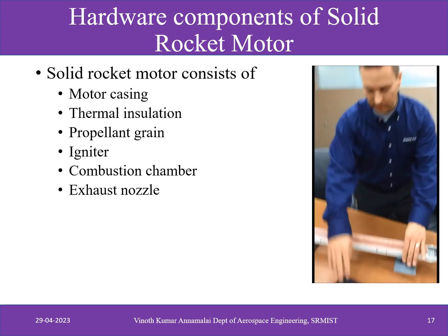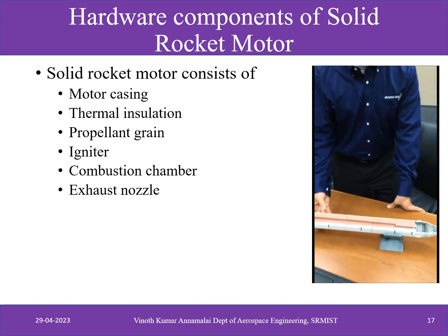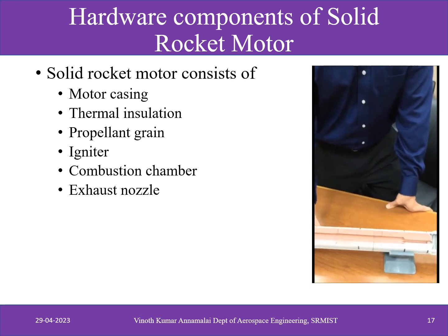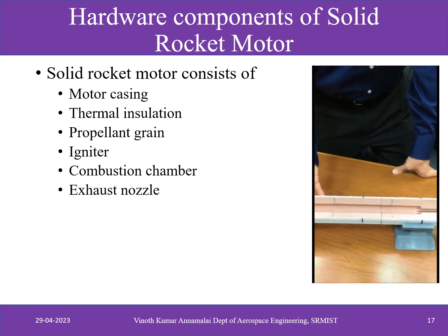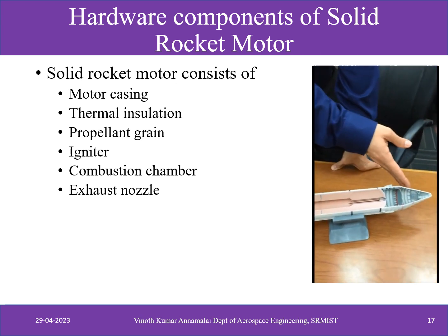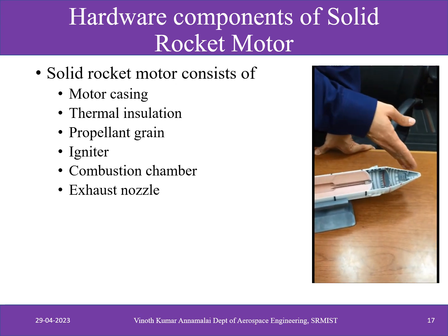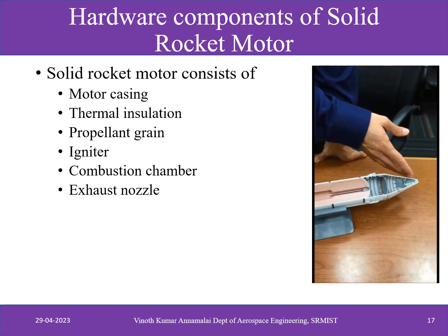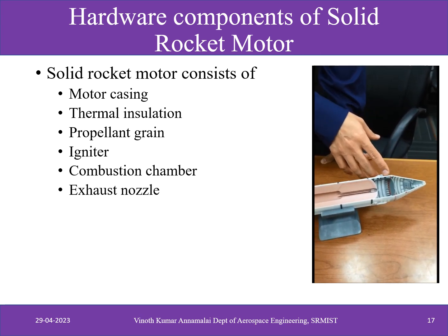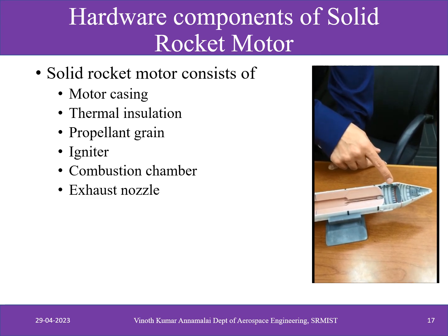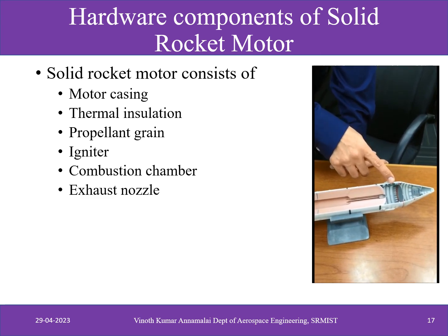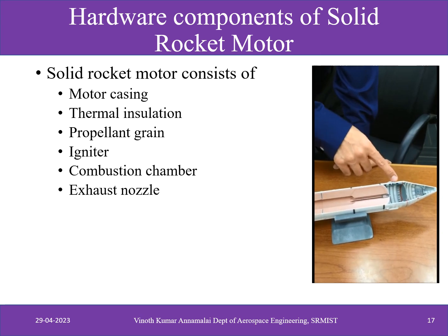So this is a model of the booster. Okay. What am I looking at here? This is a model of the SLS booster. What you're looking at, the top end, if this was stacked vertically, this would be what's at the very top. Here's the nose cone, and this is what we call the forward skirt. And inside this forward skirt will be all sorts of avionics boxes, the control systems for this booster, as well as they integrate to the core stage of the vehicle.